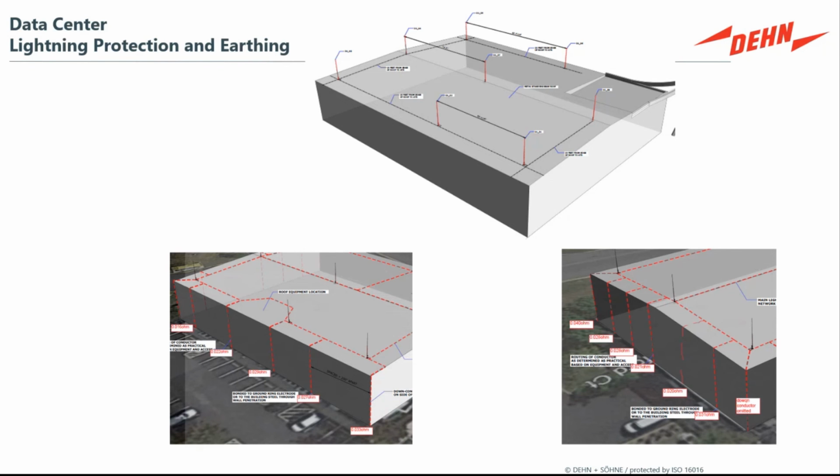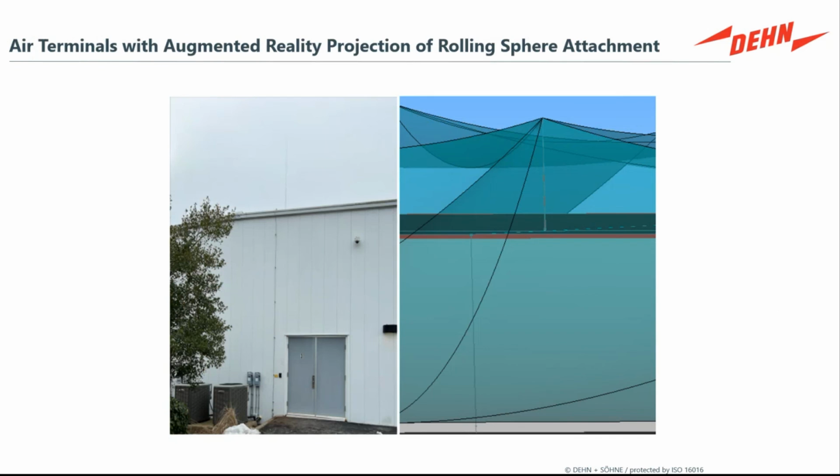In a legacy structure, you may not be able to get to a side that has otherwise been completely filled with concrete or asphalt or other limitations from electrical services. So here we've applied the principles of the lightning protection calculations for the number of down conductors and applied them appropriately to meet the standard, and really it is a matter of the challenges that you encounter at a site.